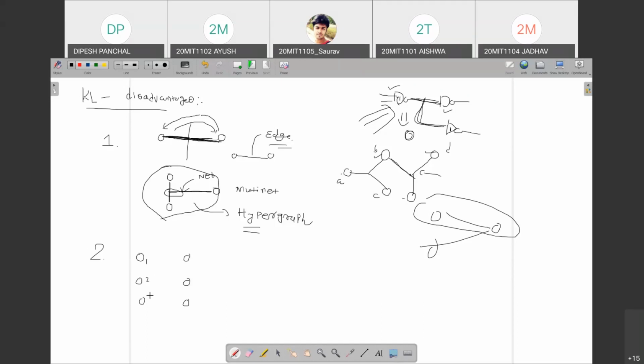Let's say 1, 2, 3, and the size here is also 1, 2, 3, or some 4, 5, 6. Let's say the size of each node. If you do the swapping, does it remain the same size in this partitioning and this partitioning? You do the interchange. Size is what we assumed previously in the KL algorithm. We assume that the size of each node or gate is the same, equal size.